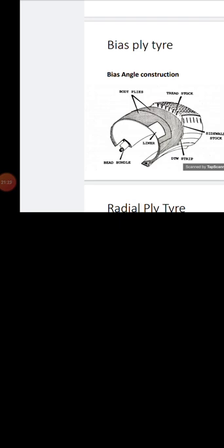As it comes out from the footprint, the tire rapidly expands and goes beyond the natural point into a stressed position, opening the tread, and as it moves through the contact patches this is one of the major causes of normal tire wear.